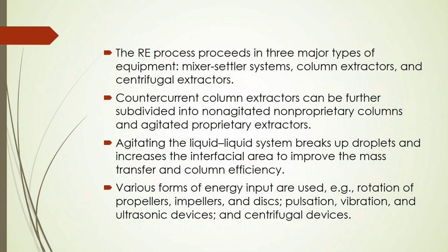In an agitating system, the liquid will be broken up into finer droplets or finer bubbles, which may increase the interfacial area to improve the mass transfer, and also the reactor efficiency.